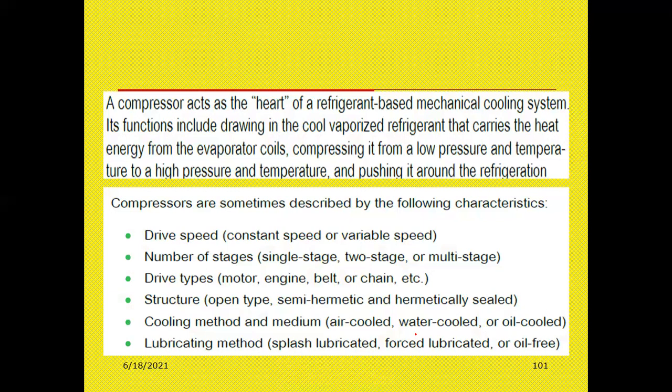How do we do lubrication in the compressor, how do we send the lubrication to the compressor whenever it is in action? We have various methods: splash type, mist type, forced lubrication, and oil-free lubrication. So we have various methods of pumping the lubrication into the compressor.